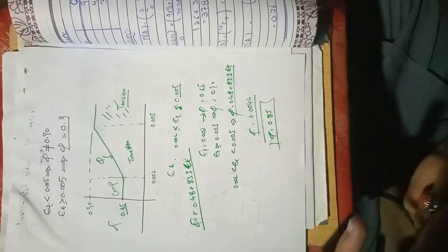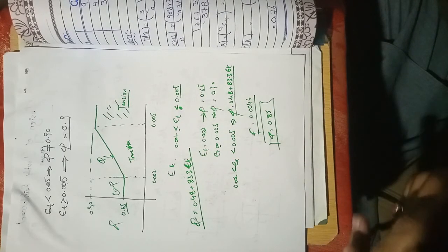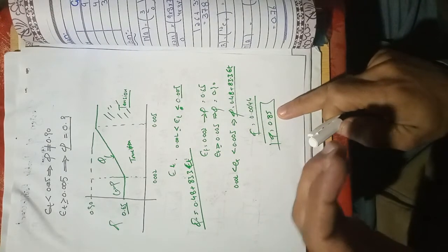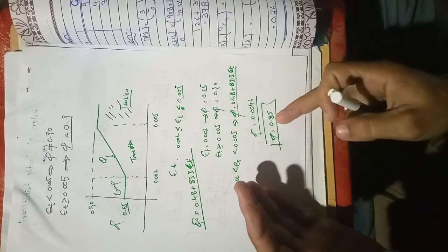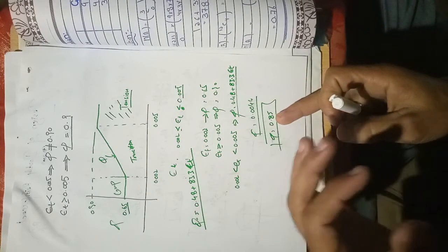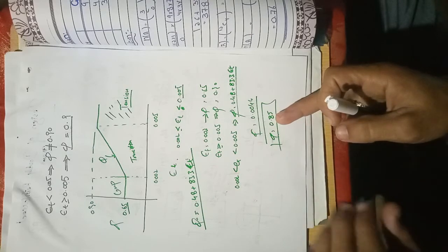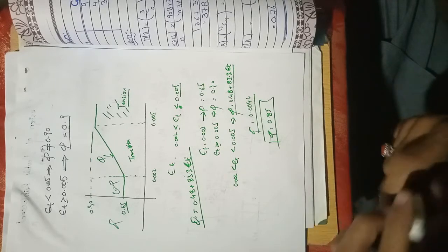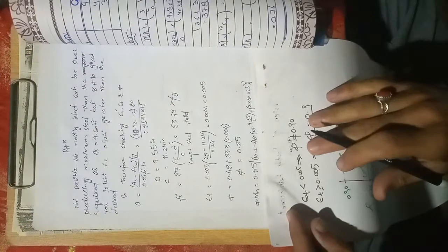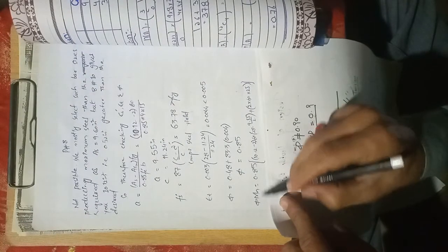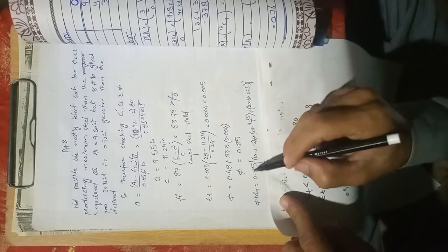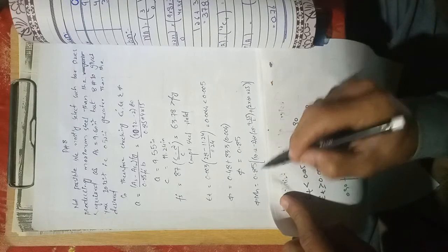So the effect of this value is that it will reduce the capacity of your moment. Because from 90% to 85% we have a 5% further reduction, so this will further decrease the moment capacity of your section. So let's see how it affects the ultimate or the moment capacity. We are again using the same moment equation. Now we are using 0.85, not 0.9, because we adjusted this value.